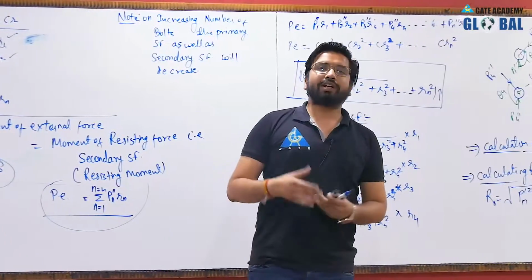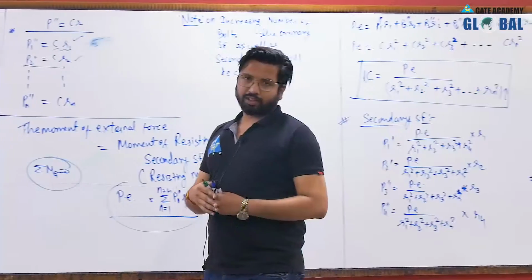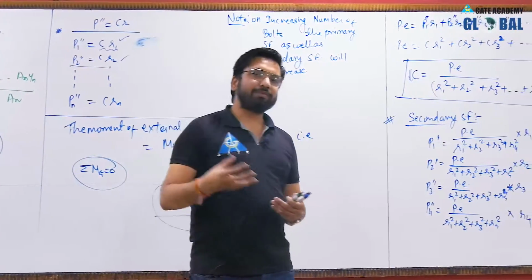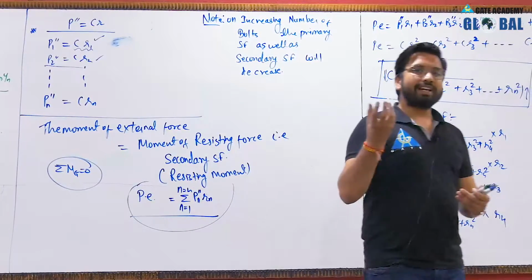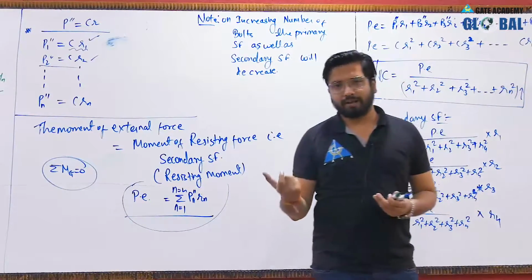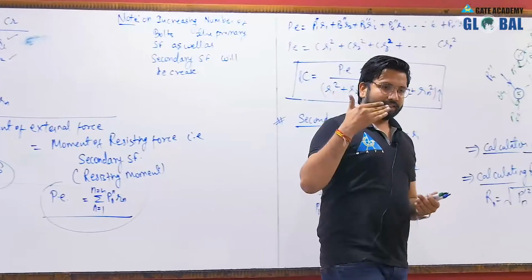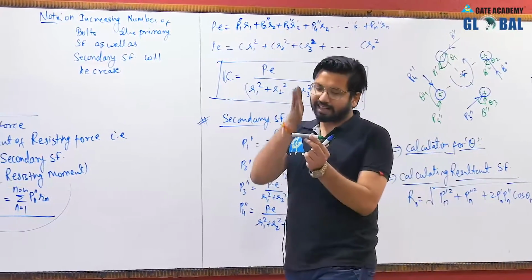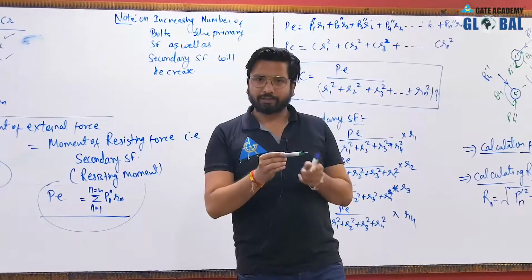Okay, because in order to solve the problem based on the core diameter, we must have a manufacturer catalog so that we can refer to a proper value of major diameter. So here, as you can see, there will be two possibilities in case of shear. The shear can take place at the shank and at the thread portion as well.